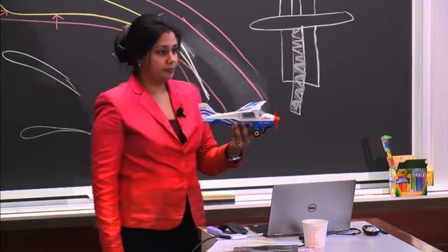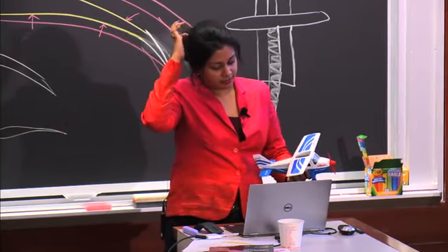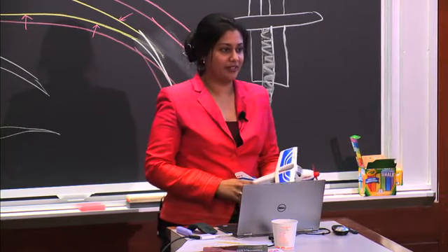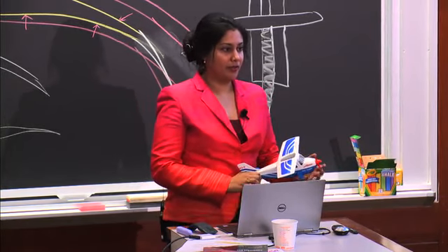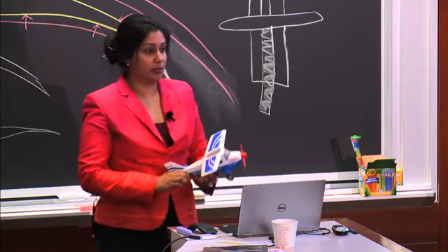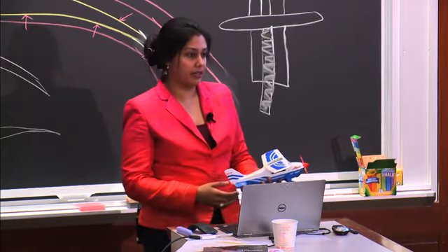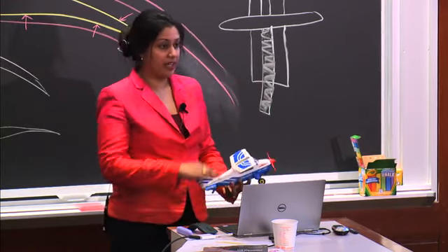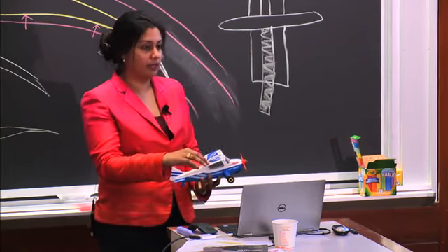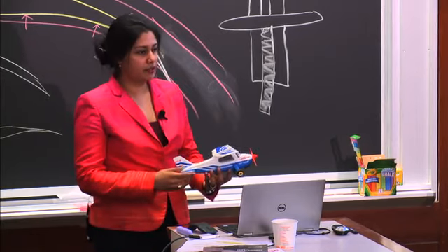So it is not 90 degrees ahead because of precession? Precession is separate. It is generating its own factors and dynamics. So both of these things are acting at the same time. Precession does, in fact, affect pitch, just like you correctly recognized. But this is an additional factor: since the center of thrust has actually moved to the right, it's causing the yawing. Did that answer your question?